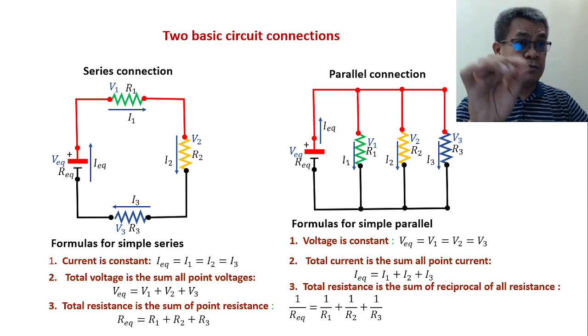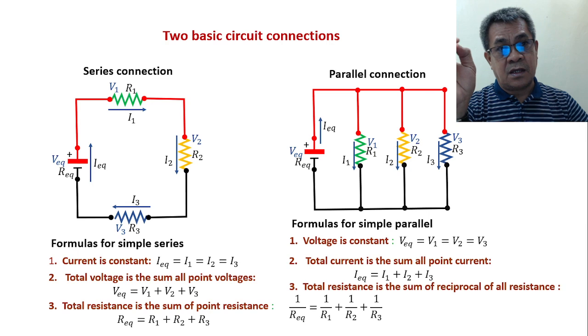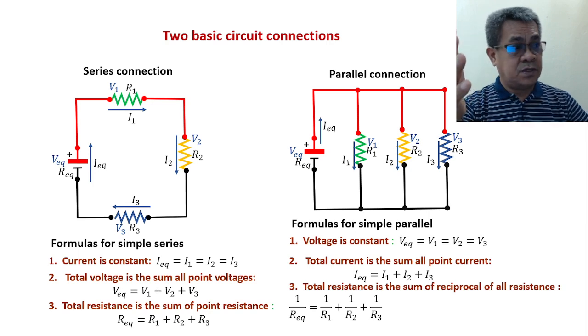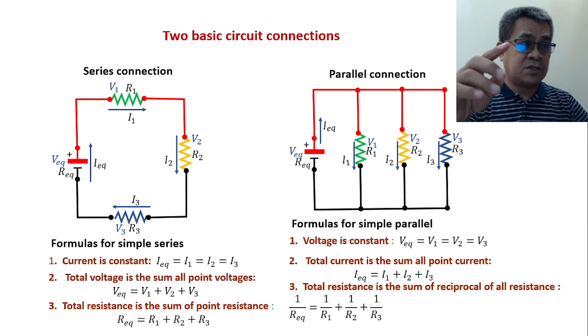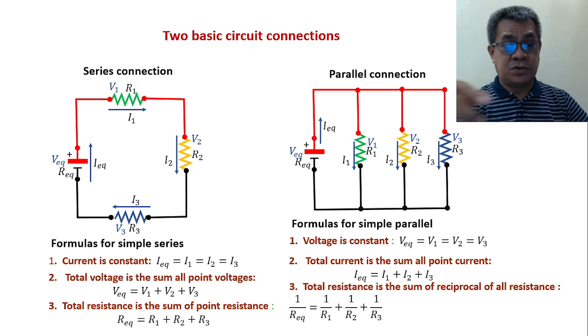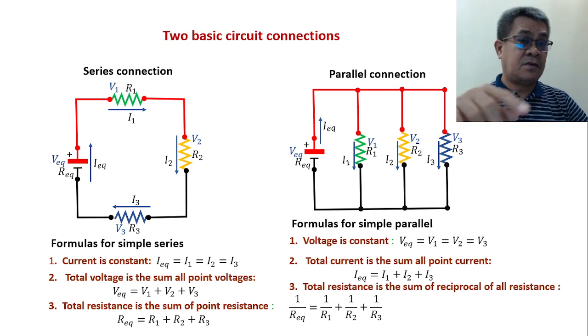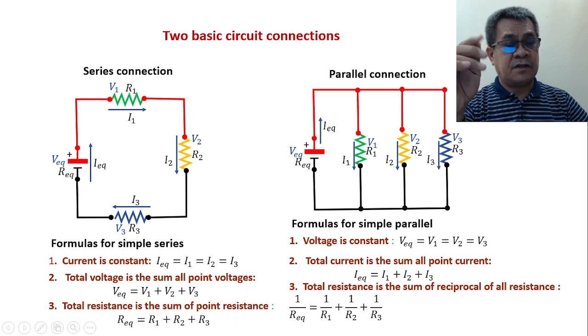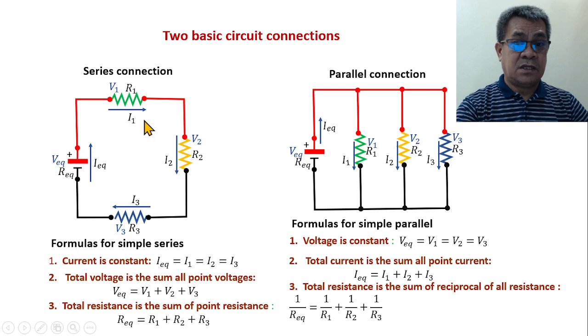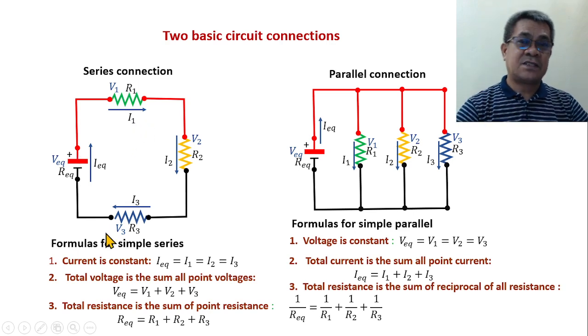So it should be connected in parallel. And the bulbs that we use, the appliances, are all supplied by, most of the time, 220 volts in our case. So therefore, household should be in parallel connection. But in Christmas lights, for example, it should be in series.